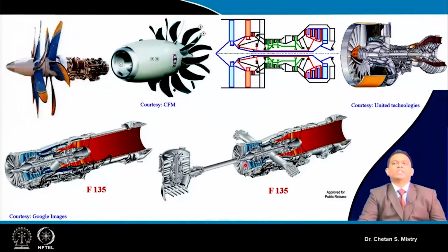Now this engine is fitted on an aircraft having a VTOL configuration. It has vertical takeoff and landing, and for that purpose they have fitted a fan configuration. That fan is also a contra-rotating configuration. You can see it here. This is giving benefit in terms of vertical takeoff and landing. So the development and use of the contra-rotating fan has been proven, and this engine already exists.